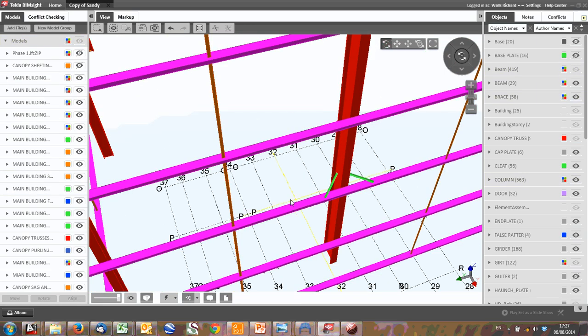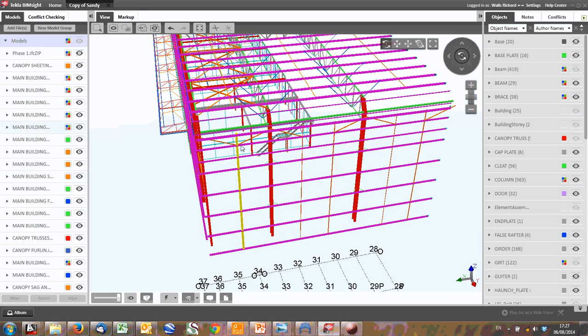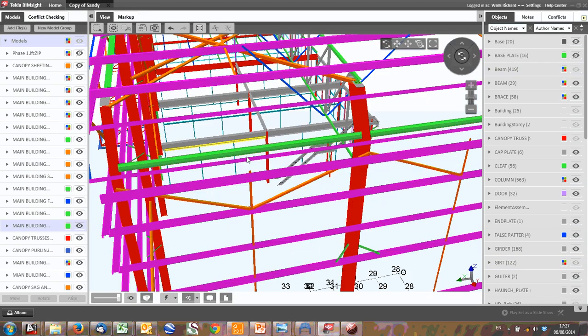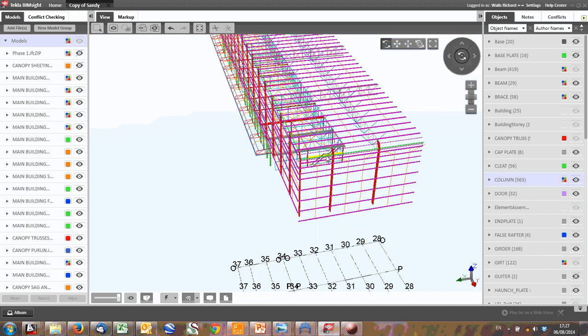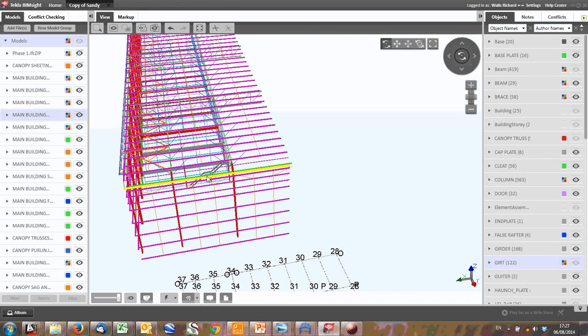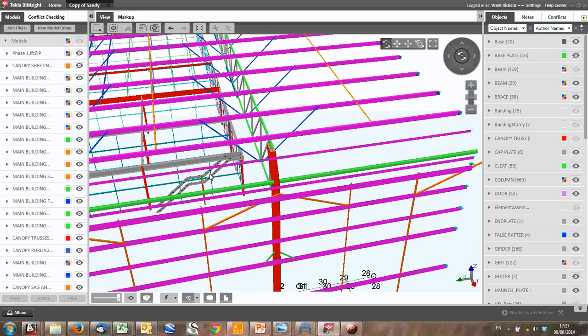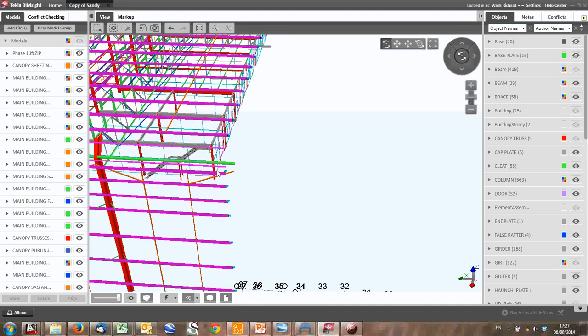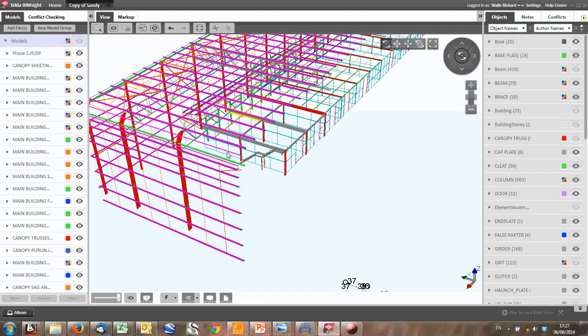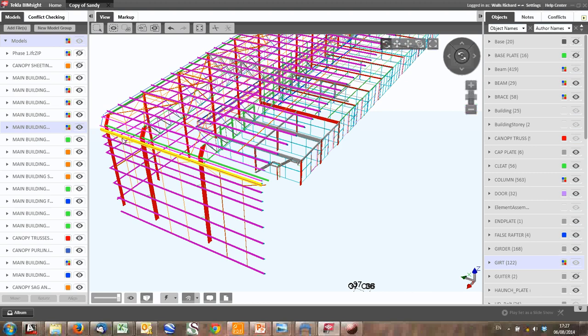Uh-oh, no vertical bracing. Why is that? Why is there a problem? Well, not actually, because that load came along, and then we transferred it down these pipes, those horizontal circular sections, into the existing building. So the existing building, which you can't see here, could support it. There was a stiff brace bay here. So you can also transfer load down things through pipes.